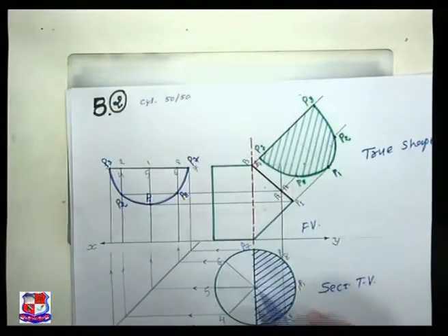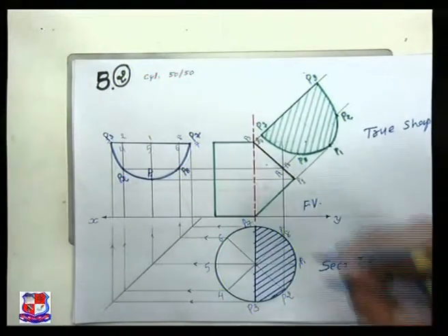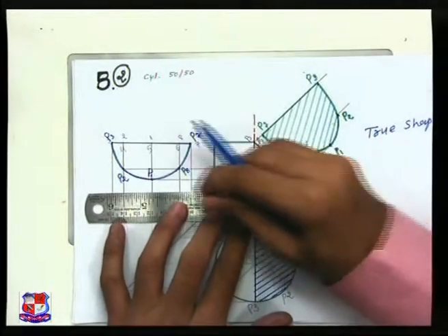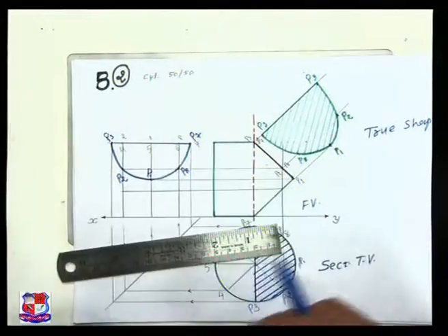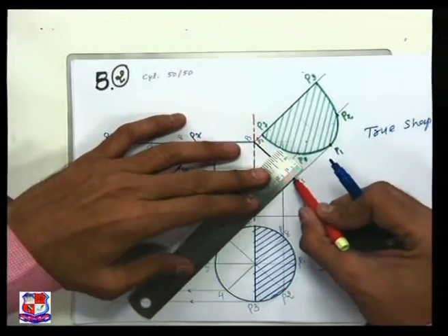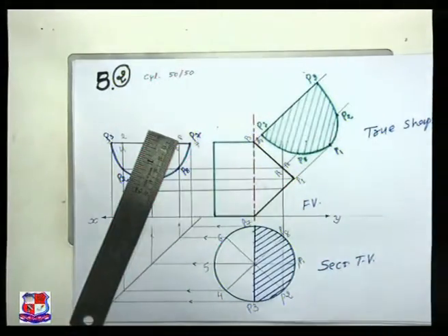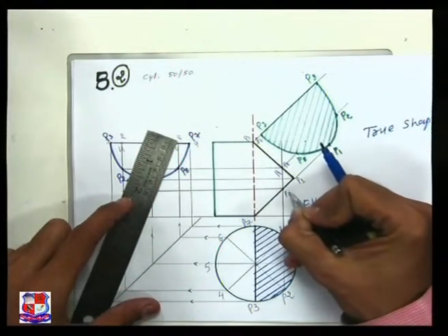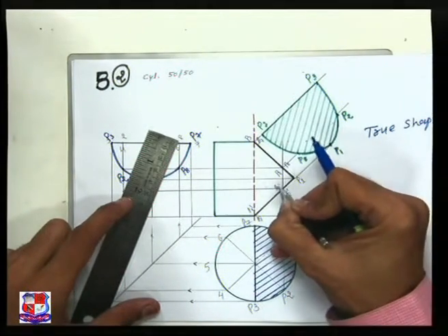So this cylinder is also cut over here. So here also the same procedure should be repeated. Take projections from the cutting plane and imaginary generators. Here the cutting plane is this one. Let me mark it with the red color line. This is the cutting plane, an intersection of this cutting plane and various points, various generators. P1 is here, say here P2 dash, here P3 dash, P7 dash and P8 dash would be there.